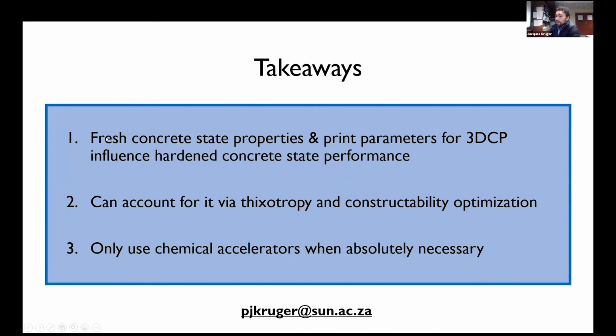So, takeaways. The first one: fresh concrete state properties and print parameters for 3D PC influence hardened concrete state performance. This is really the first one that we should know for 3D concrete printing, that the design process in the fresh state will influence your hardened state performance as well. But number two, we can account for it via thixotropy and the optimization process. And lastly, only use chemical accelerators when absolutely necessary.